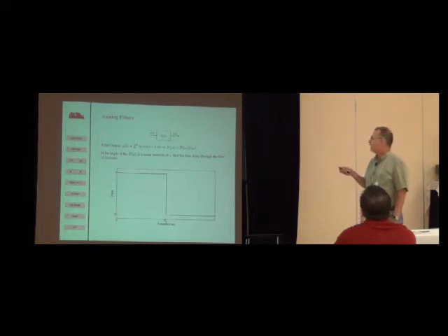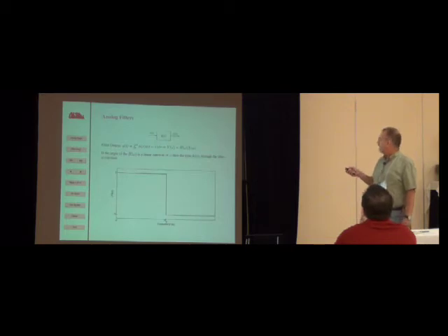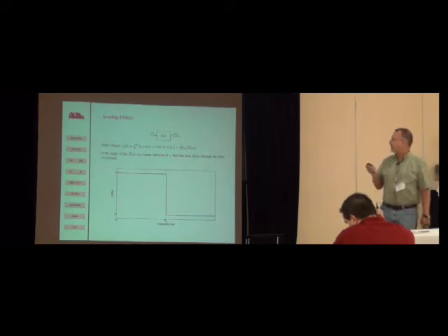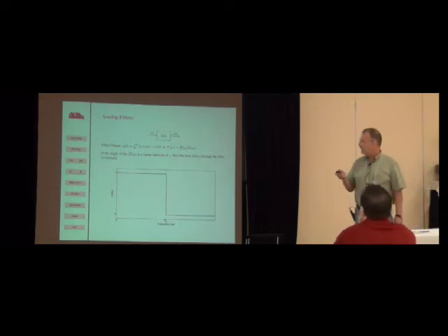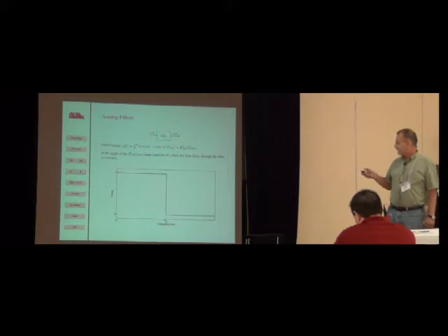And so you can achieve this if you take this complex expression, H of omega, and write it in polar form. If you look at the angle of the phase, if that's a linear function of frequency omega, then you're guaranteed that the time delay through the filter is constant. And you can establish this by the topology of the filter. So what you're left to design is the amplitude response.